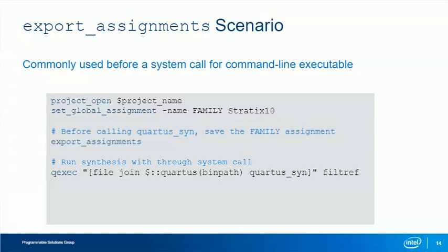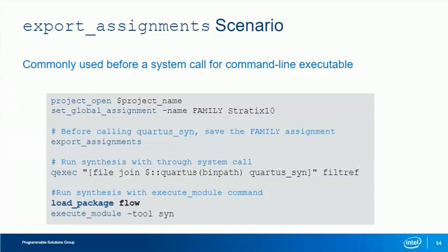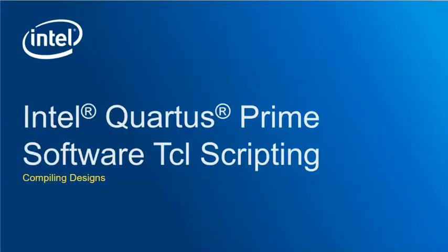On the other hand, if we use the execute_module -tool syn command instead of using the qexecute system call, we don't need to export assignments because the execute_module command will automatically commit settings to the QSF. Now that we've talked about how to use Tcl to create projects and make assignments, let's talk about how to use Tcl to compile designs.